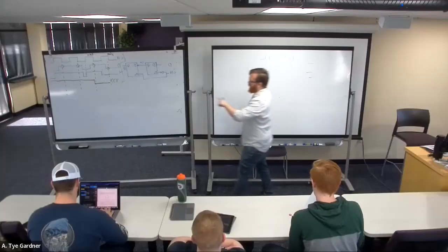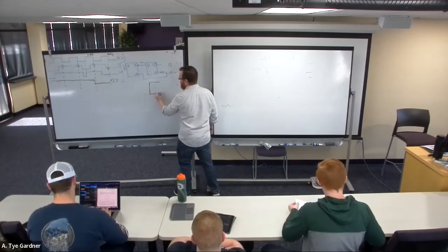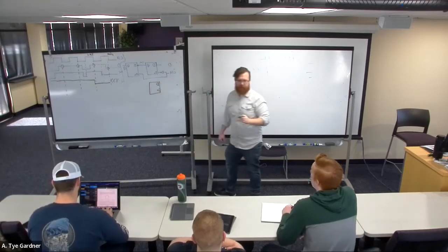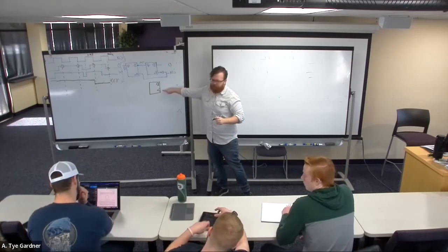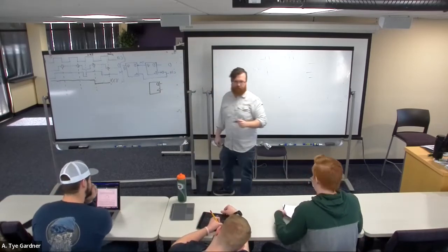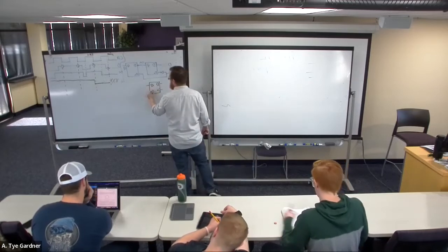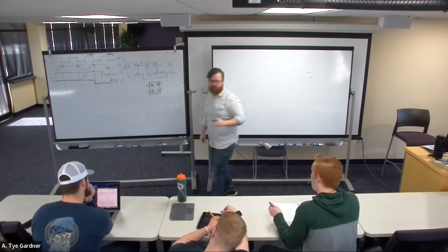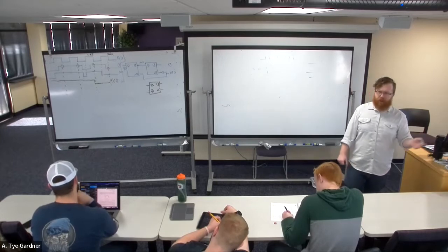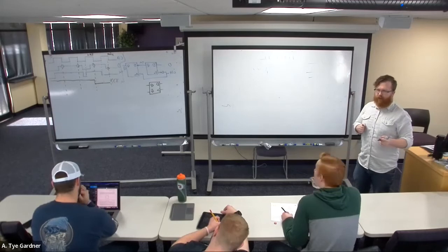Oh, and when we combine them in this type of architecture, we redraw it as a D flip-flop, which has a D, and then a little flag looking symbol, like a little pennant flag, that means there's a clock input. That's all that symbol means. And then it has a Q and Q bar output. We don't always have to draw the Q bar output on the schematic symbol unless we're using it, but be aware that because of the way we've built this, there's always a Q bar available, right?